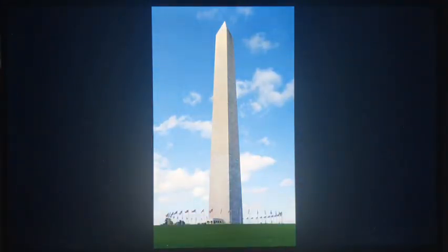But just think about the Washington Monument and the way that it is also this classical form of architecture, just one single column. And with the Washington Monument, this is not just like a post, like one piece of stone carving this column. This is a skeleton and skin construction. We have a steel structure that has then been sheathed on the outside with stone.